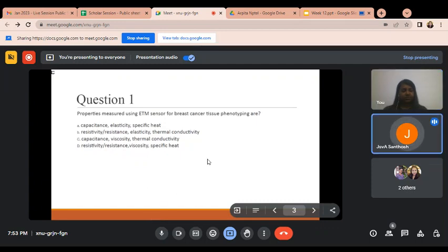Yes, ma'am. There are two techniques. You already told us physical evaporation and chemical evaporation. But for gold, which process will we use? Actually, for gold deposition we mainly use the PVD system. So we can use sputtering, E-beam evaporation, and also the thermal evaporation system.